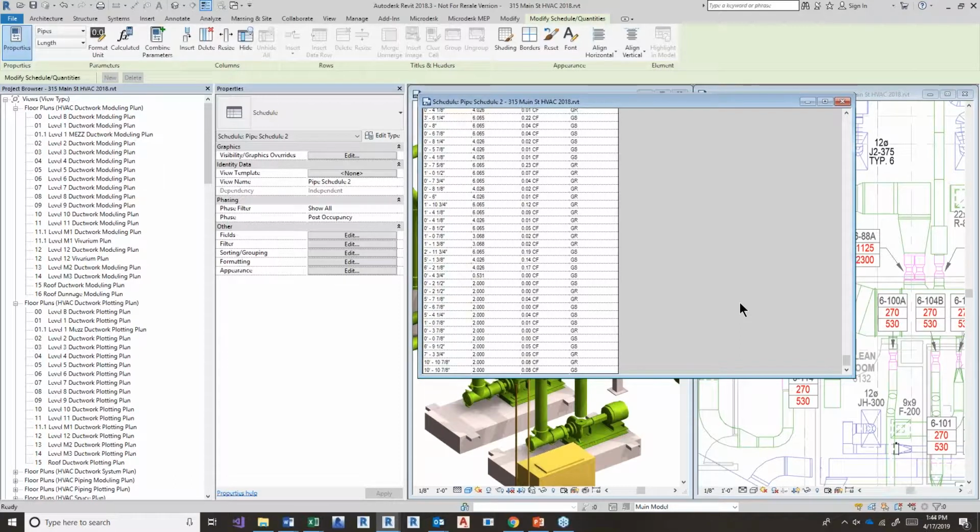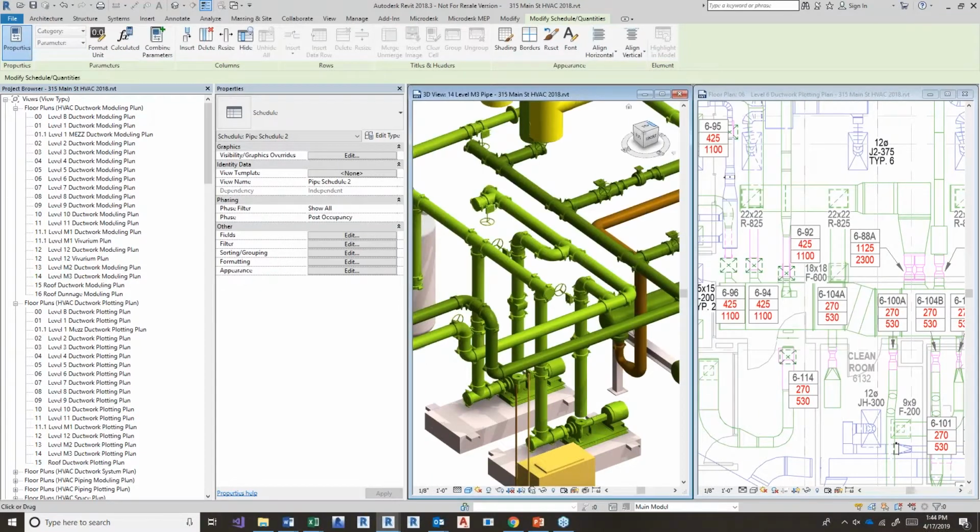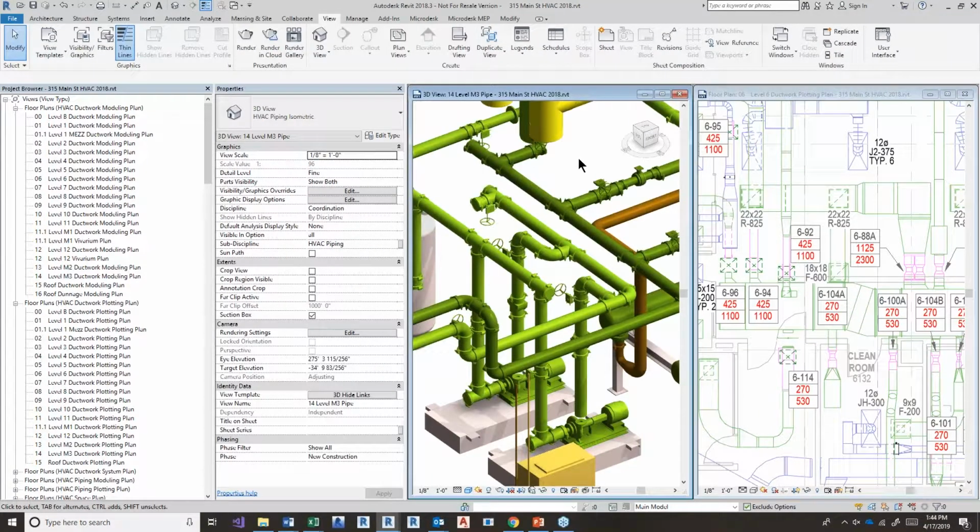So with some of these options, there is an out-of-the-box way to do it. It takes a little bit more in-depth Revit knowledge. And if somebody just wanted that raw data dump and they're fluent in Excel, with a couple button clicks, we can export that information very quickly. And then furthermore, if we're editing in Excel, we have access to some tools and some search features that Revit simply doesn't have. So we can make those edits in Excel, round trip the information, and validate the quality of the information.